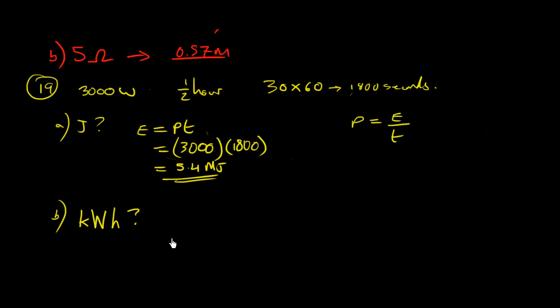And what is a kilowatt hour? Well, it's a strange unit, but it's the same thing as energy. It's another measure for energy, right? How do I know that? Well, I just said before that the power, which is what kilowatts is, thousands of watts, times the time, which is hours, equals the energy. So, in other words, this has the same units as joules, except it will be quite a few joules, but it can be written in joules. So what is 1 kilowatt hour in joules?